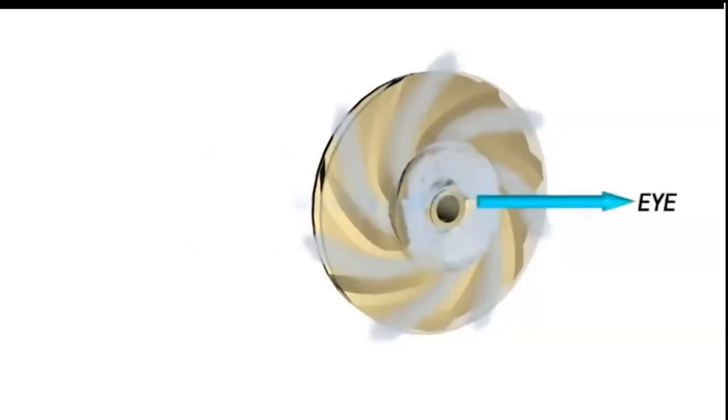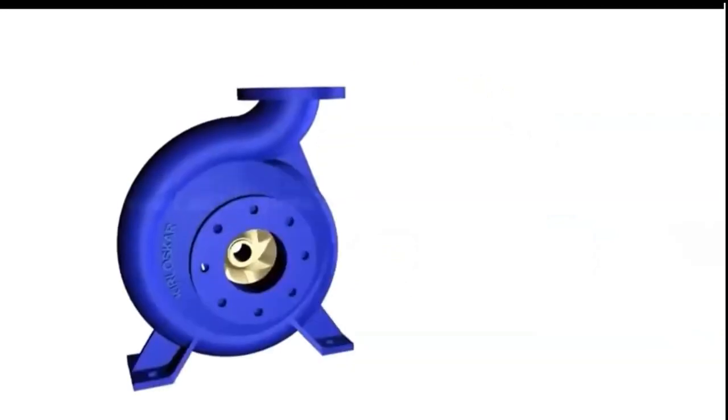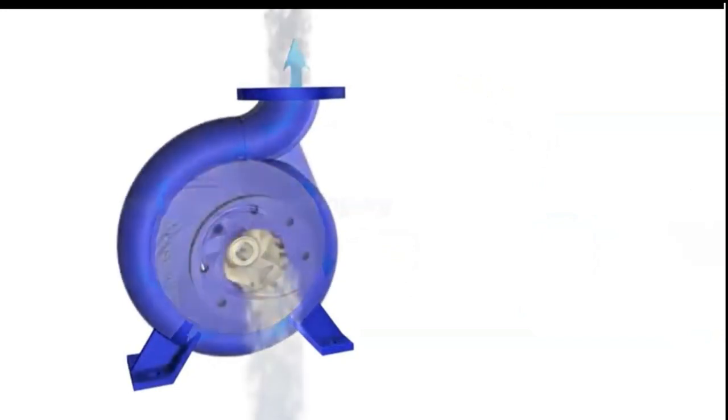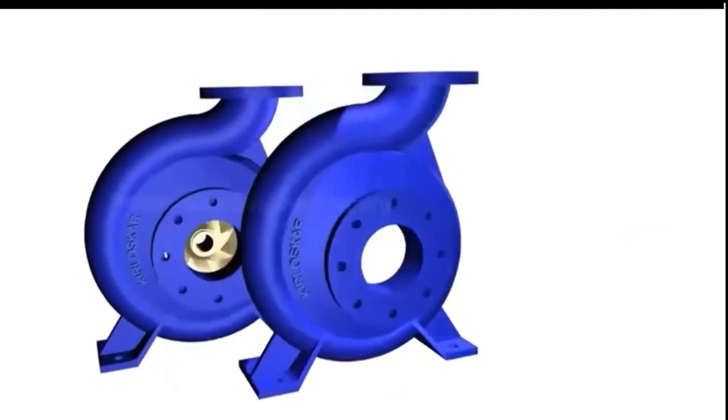As the impeller rotates, fluid is sucked in by means of pressure gradients. Fluid flows radially through the eye to the edges of the blades to what is called a casing, a housing or volute. For the simplest type of centrifugal pump, the fluid is discharged directly into the stationary bowl-shaped casing with an increasing area in the direction of the flow. This helps to reduce and also produce a more uniform velocity distribution of the fluid as it moves from the eye to the discharge opening. This reduction of kinetic energy favors an increase in pressure.